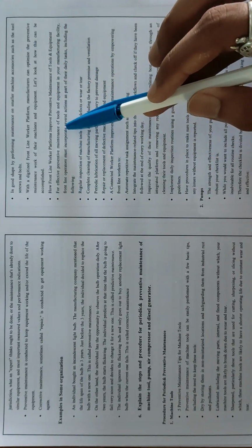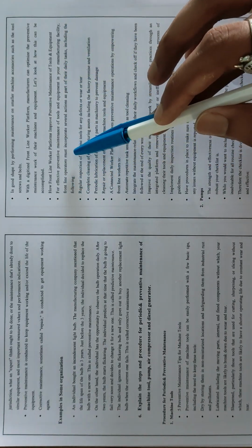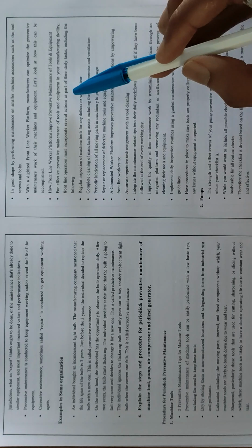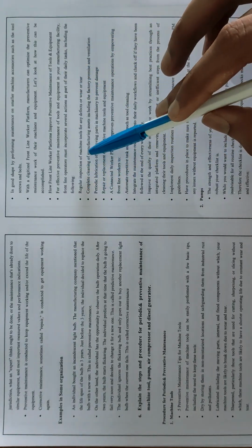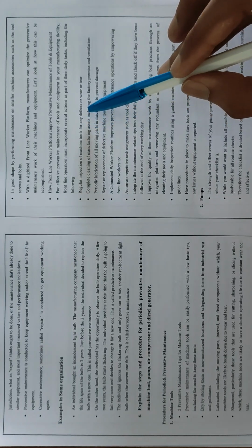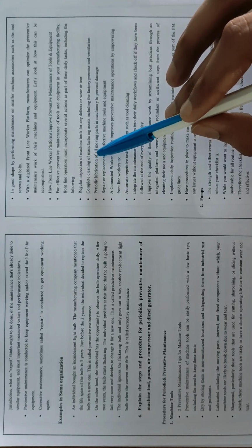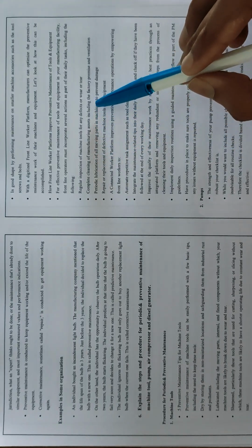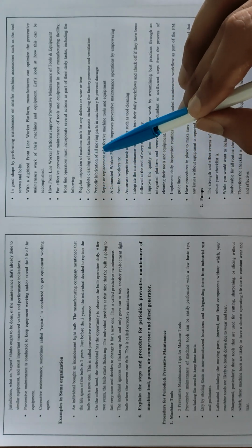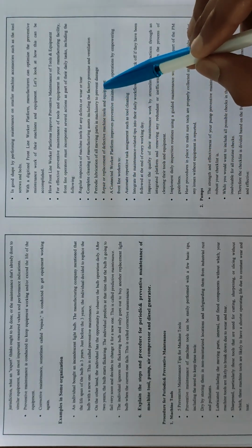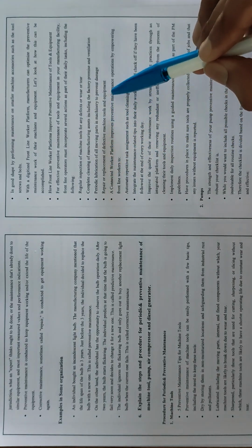For effective preventive maintenance of tools and equipment in your manufacturing facility, frontline operators must incorporate several actions as part of their daily tasks, including the following: regular inspection of machine tools for any defects or wear and tear, complete cleaning of manufacturing assets including factory premise and ventilation, periodic lubrication of all moving parts in machinery to prevent damage, repair or replacement of defective machine tools and equipment.